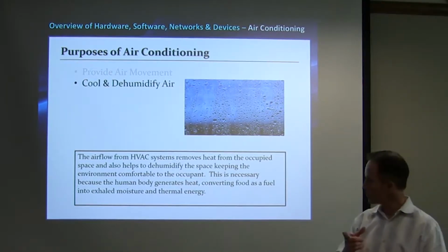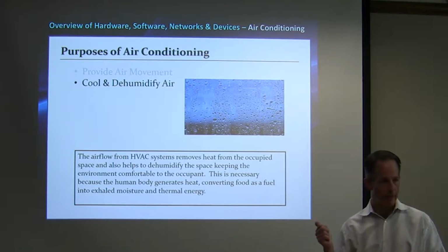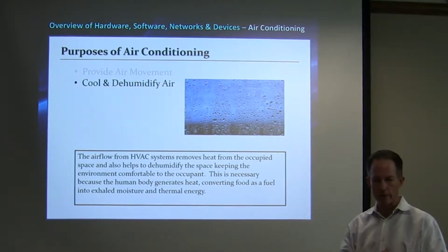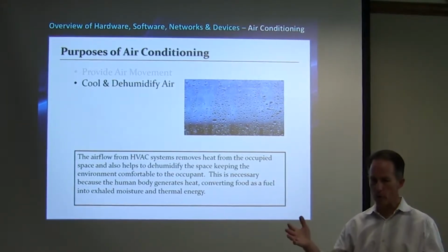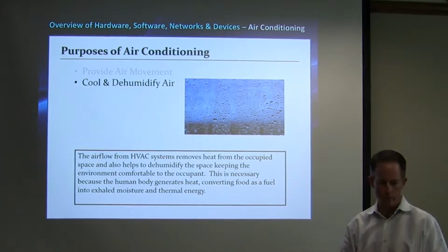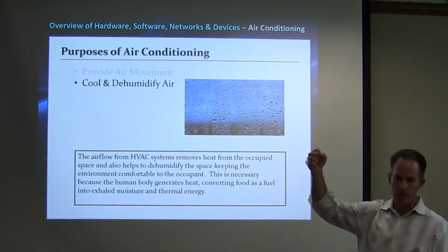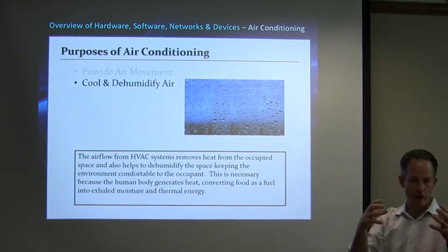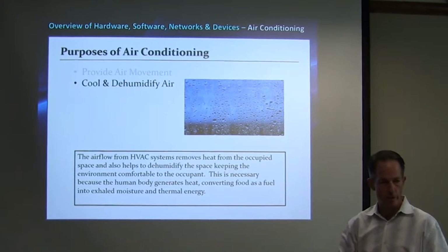We talked about, it was mentioned, cooling and dehumidifying. When we dehumidify, well, how do we primarily do that? Okay, the colder the air, as we cool air, what happens to the moisture in the air? Okay, just like on this picture, right? We get water vapor starts to condense onto that colder surface. It drops out of the air, and thus we remove the moisture from the air.